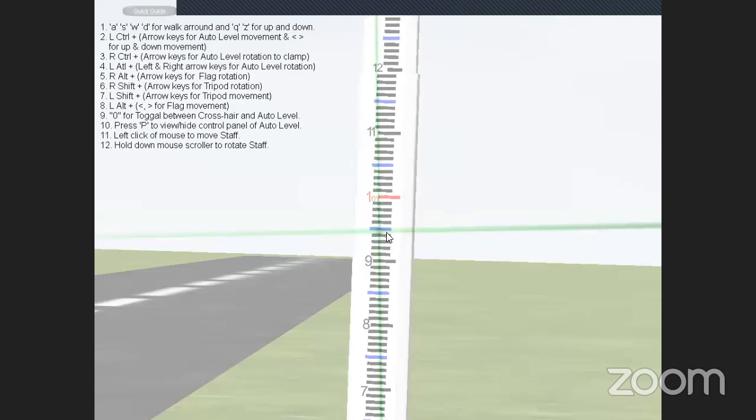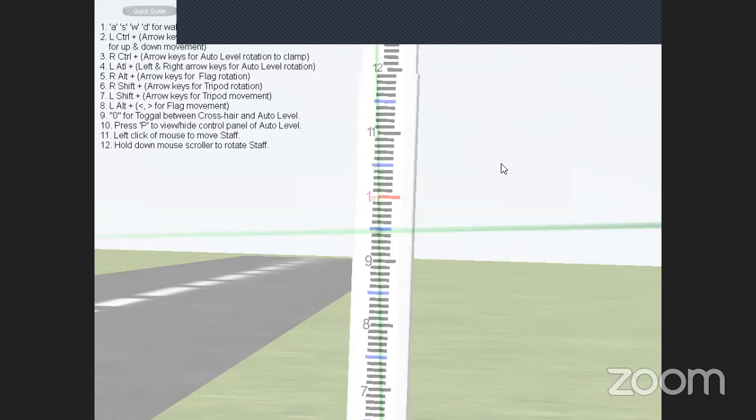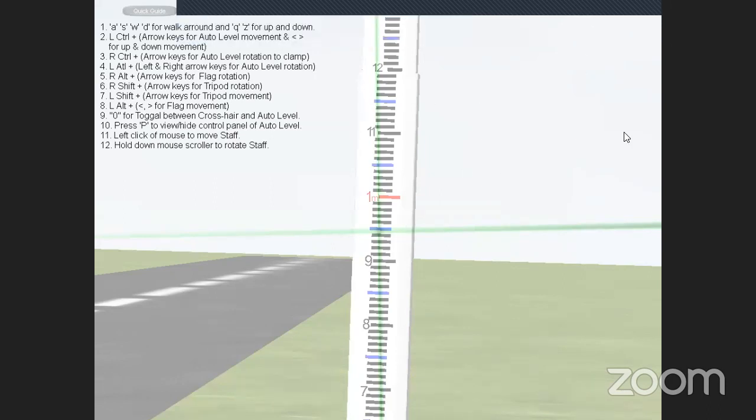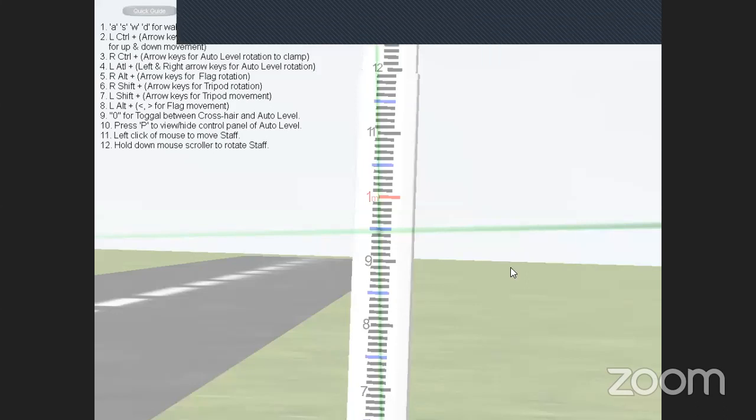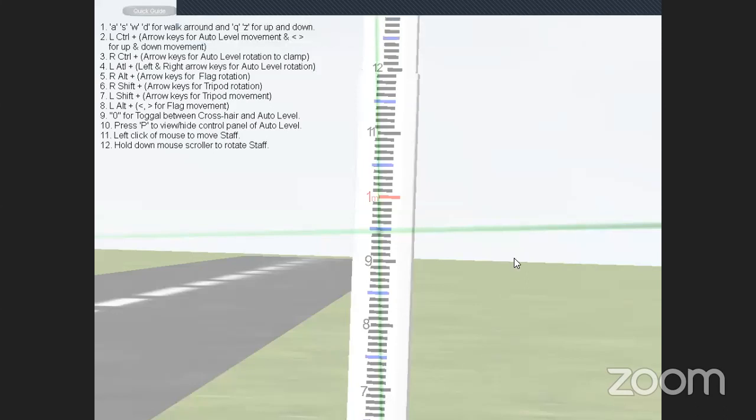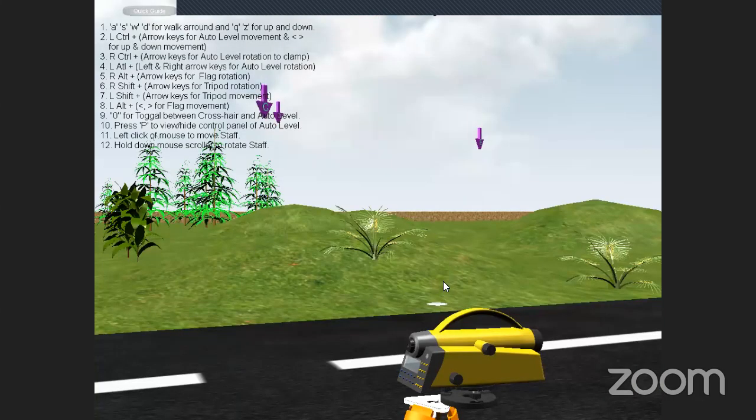This is kept at a benchmark, so it is a back side. The station is benchmark. In the remarks, you write benchmark and you note down this reading as 0.95 meters or 95 centimeters, whatever you want to write. And the RL of the benchmark is given as 250 meters. Now, what I have to do?